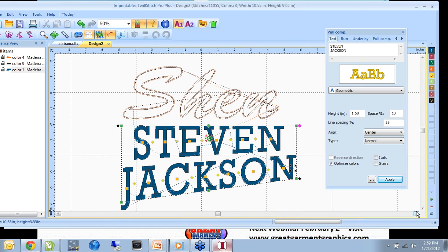Okay, and last question is, can you import an art file from Corel to work with? You wouldn't import a CorelDRAW file, a CDR file. What you would do is import either the encapsulated PostScript, or in Corel you can save it as that PLT file, a plotter file. And that's the plotter file I found is the best one to work with in here. So in Corel you simply export it and you choose the plotter file function. If you have a CorelDRAW file and it's the only thing that you have and you don't have CorelDRAW, well, you could probably contact me and I can convert it over for you. So that's a quick and easy way.